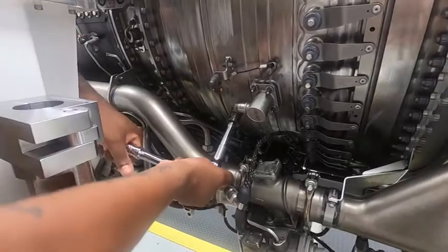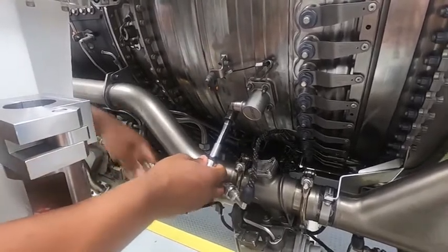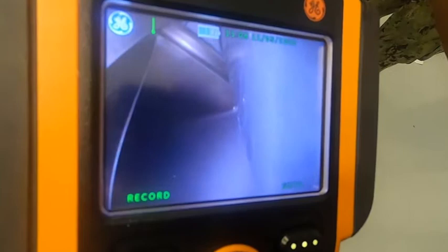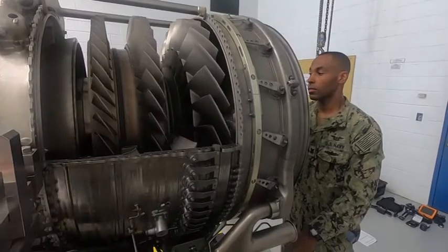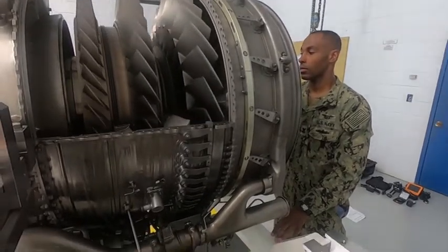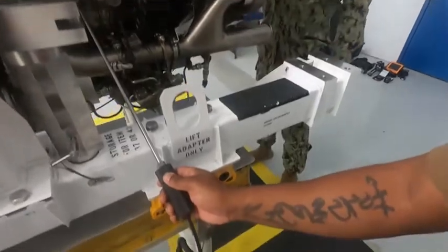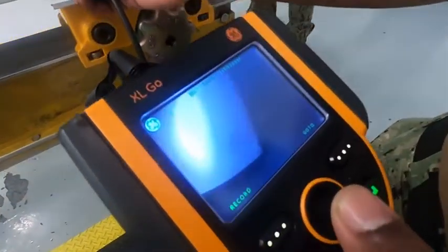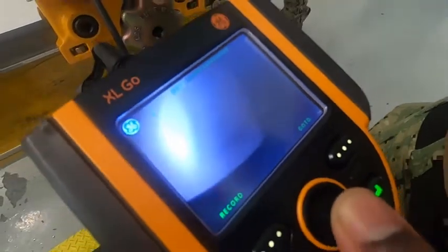Before starting the inspection, remember to mark a blade to ensure a full rotation of the fan has been completed. Now that the engine is prepared for inspection, we can begin by removing the borescope plugs and inserting the borescope tip. All right, go ahead and spin. You need at least 2 people to perform a borescope inspection. One person to hold the borescope and inspect, and a second person to spin the blades or the PTS.